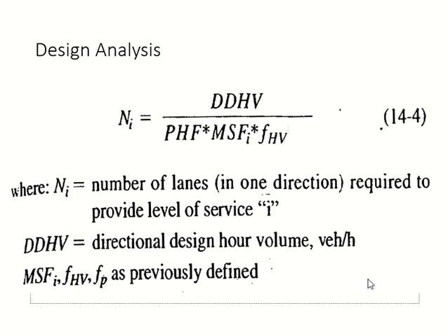Okay, this value has a separate I, right? Does the FHV have an I? This one has an I? That one? No. Okay, so the only thing changing for each level of service is maximum service flow rate. Okay, coming back to the question, why don't we design for level of service A? Because it will be too expensive.